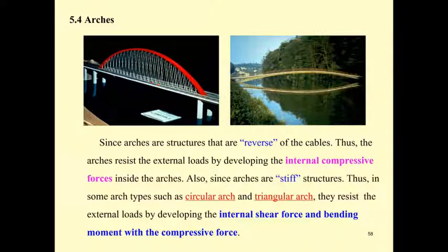In addition, if you may recall, the horizontal force of the cable is always equal to F sub h, and that helps us determine the force in the cable by the equation T cos theta equals F sub h, and then T is equal to F sub h divided by cosine theta.